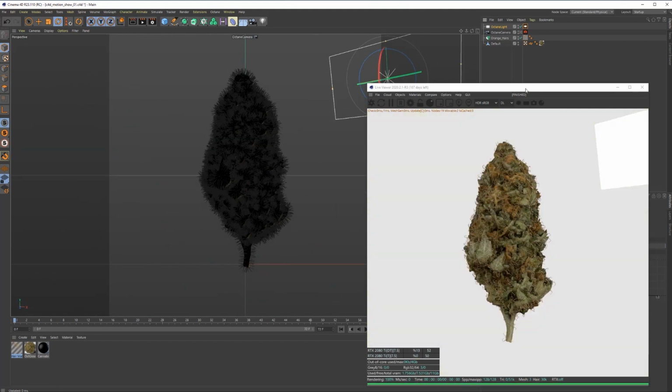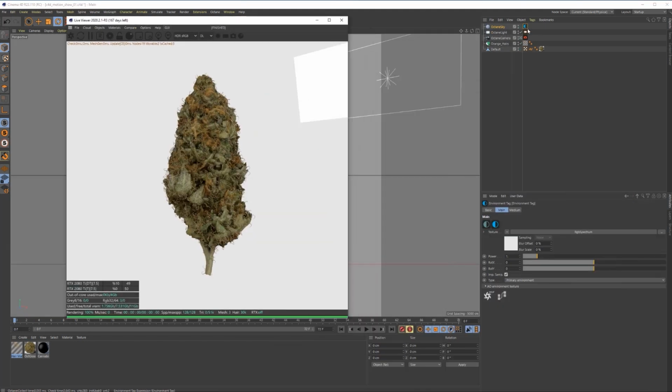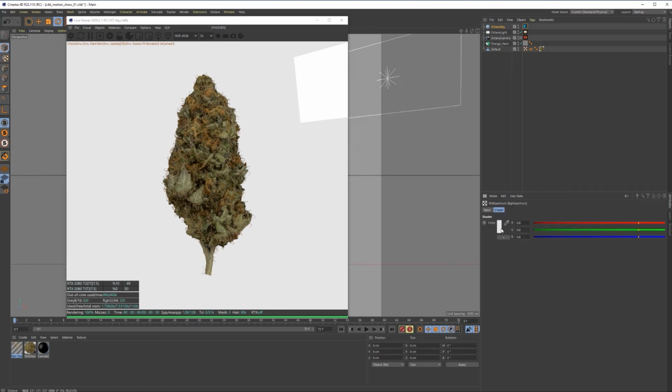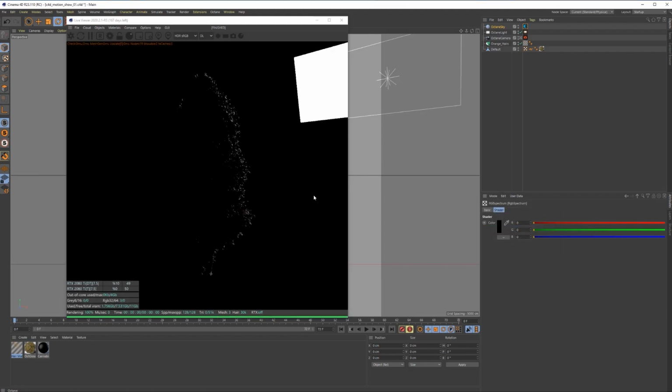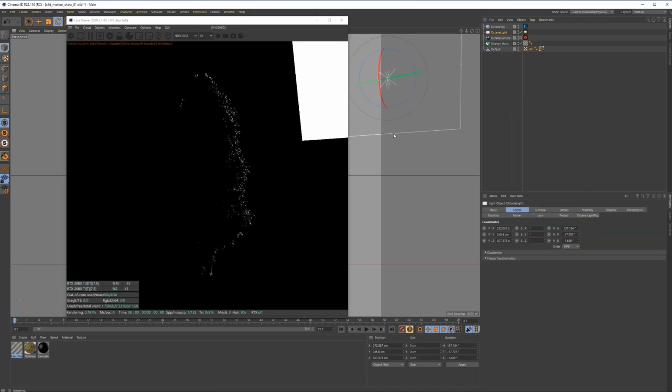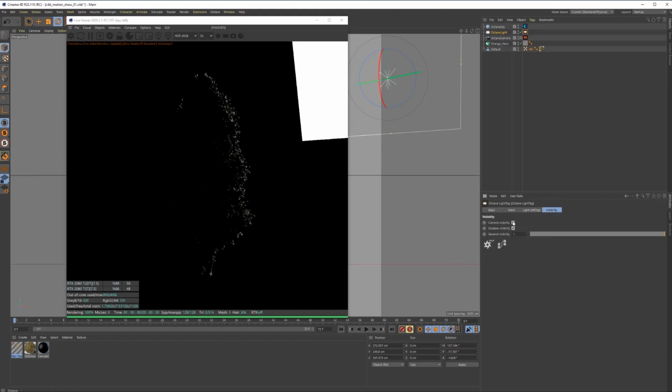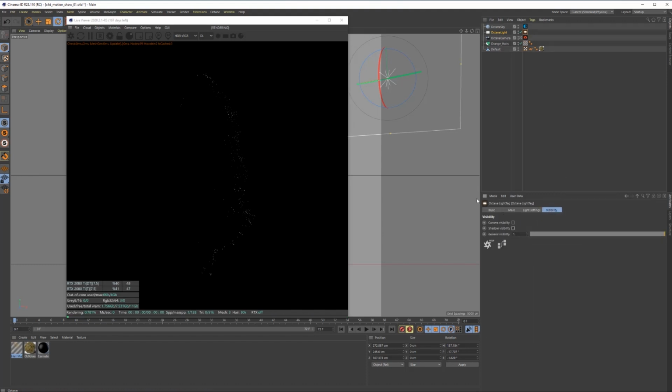Let's also add a background into the scene. Let's just say a texture environment, and let's make this black because I don't want this to be adding any kind of additional light in here. Now you can see we're really only lighting it with this light off to the side. Maybe we'll tweak this parameter a little bit. Maybe I want to make it a little bit bigger, and then let's tell it that I don't want to have that object seen via our camera.